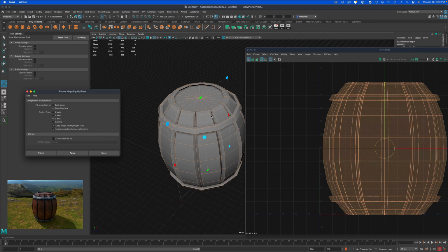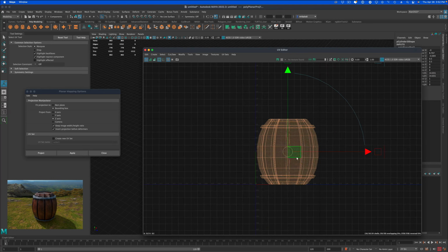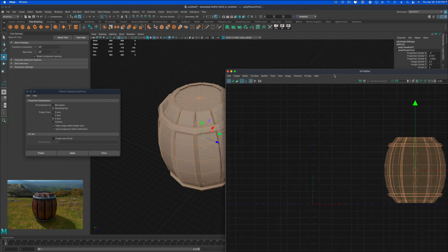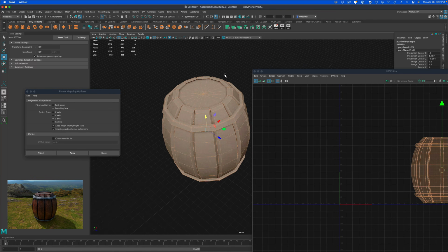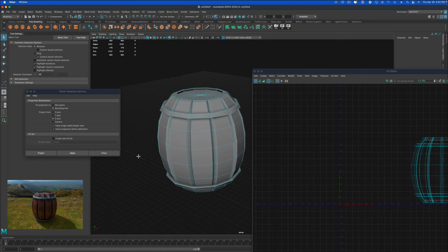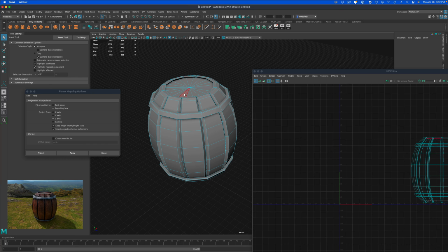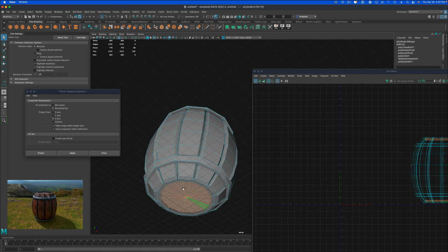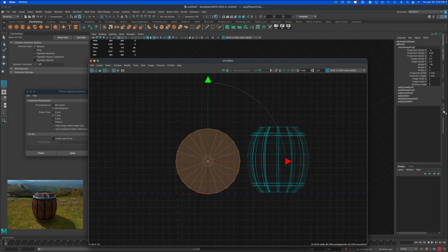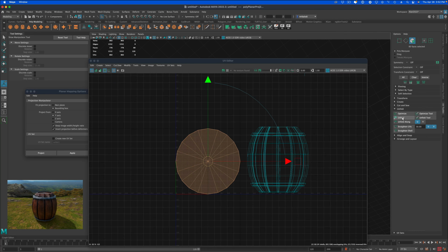So when I do manual UVs, I like to project my shape from the side so I can have kind of a pretty reference, just a personal preference. And to start, as the very first step, I'm just going to double click on the top and the bottom pieces and project them from the Y, from the top. And once I go to my UV toolkit, I can unfold them, and of course I can stack them because the bottom and the top is identical, right? So they can overlap, and that's fine.